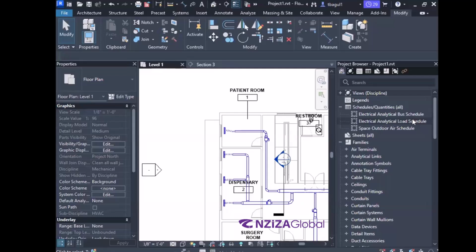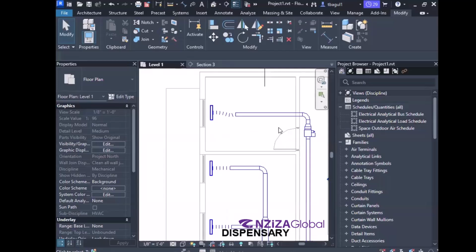You guys forgot? Okay, I'll tell you, it is not required for a patient room. For the operating rooms, it was positive. For the toilet rooms, it was negative. All right. We are supplying 85 CFM over here. If our return air register also has 85 CFM coming out of it, it is neutral.